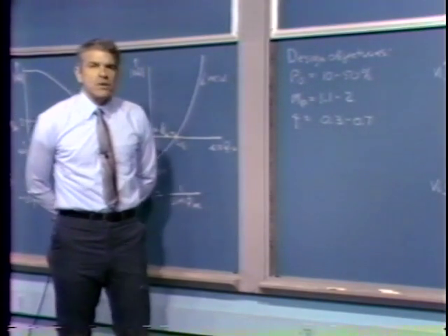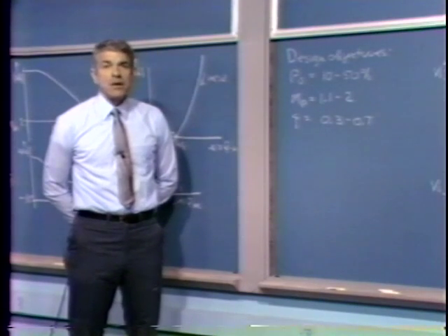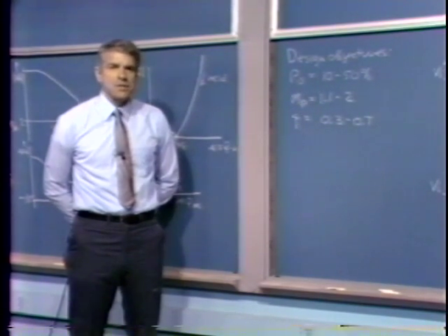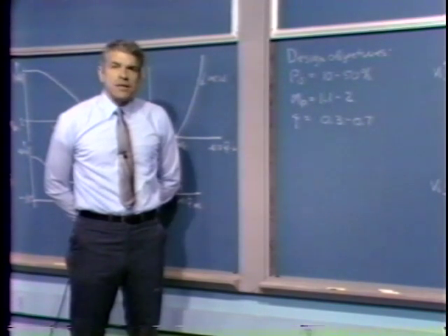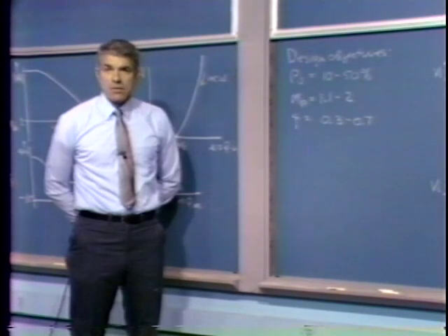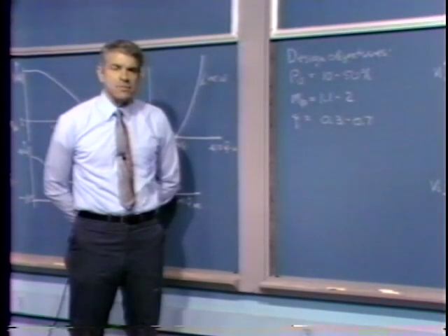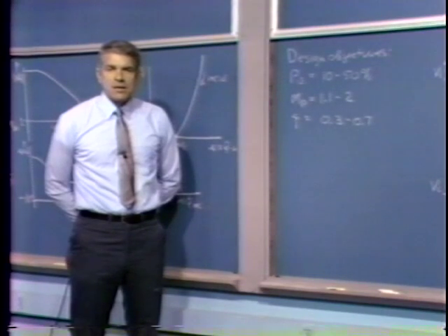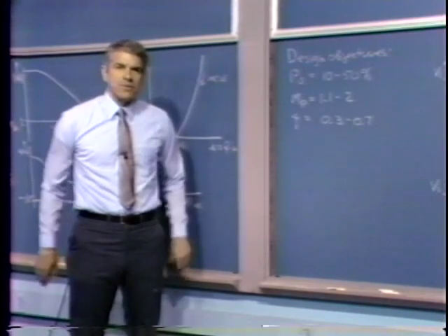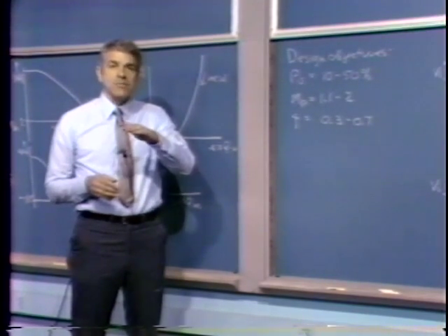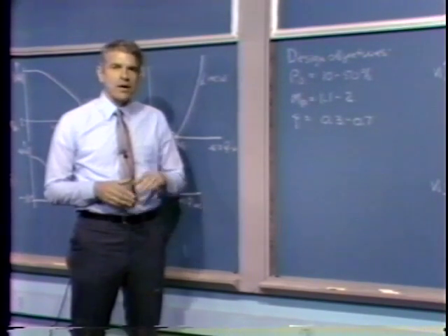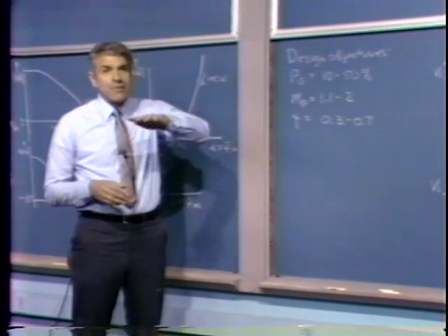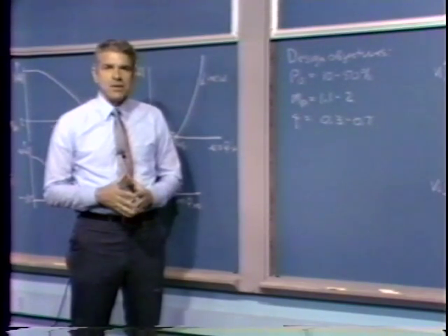And what we do is look for certain figures of merit or indicators of system performance that guide us in this design process. Well, what might be good indicators of system performance, in particular the relative stability of a feedback system? It's very hard to make sweeping general statements in that so much depends on the particular application. For example, if you're designing an aircraft landing system, the thing you want to avoid is any undershoot. And so here we have a very, very conservative kind of requirement where we have to make sure that the aircraft doesn't undershoot. That's the bad condition in an aircraft landing system.